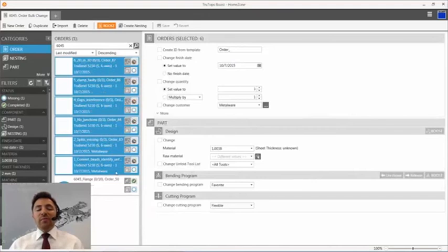Right now in the background, the parts are being imported and also already corrected. By correcting the parts, there are some rules which are applied in order to correct geometry corruptions, such as, for example, stitching faces together to a solid, among others.